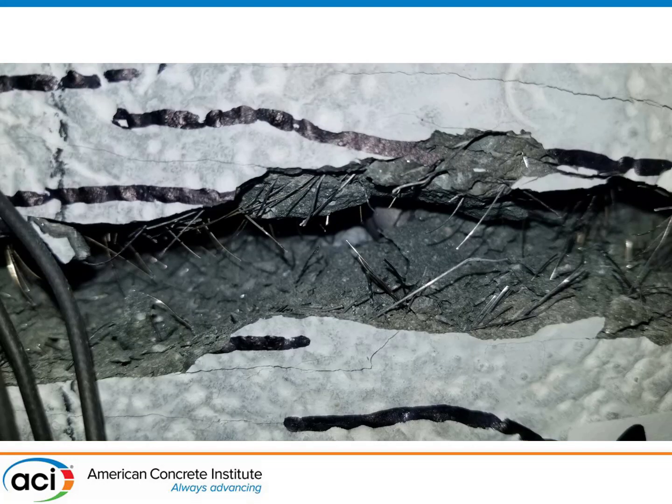This is a look into the crack at failure. If we look in the back, we can see that there is a conventional reinforcing bar right there off in the distance. And we can see, of course, the fibers after quite happily having pulled out. And that was ultimately how the member failed, pull out of the fibers. And we kept unloading until we weren't eager to actually have rupture of the bar, so we stopped the test before it got to that stage.